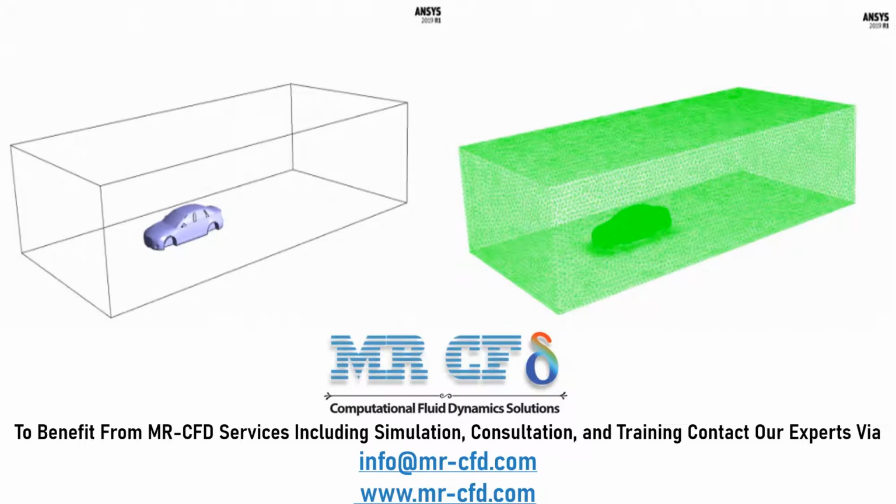The three-dimensional geometry of this model is designed using Design Modeler software. The present model includes a rectangular cube computational domain for the airflow in which a car is located. Also, the meshing of the model has been done using ANSYS meshing software, and the mesh type is unstructured. Also, the meshing accuracy is higher in the vicinity of the car surface.